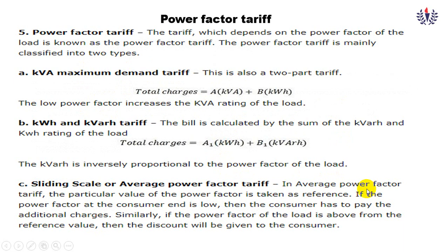And the power factor tariff. This is very, very important in case of industries. When the power factor is low, it directly hits the generating station so that it will consume more active power. So what will happen, the fuel consumption will be more, and in proportion we will get more running cost. So a power factor tariff is very, very important. The power factor tariff depends on the power factor of the load. That is the type of load I told already. I think we might have discussed it in module 2 or 3. There are three types of load: resistive, inductive and capacitive.